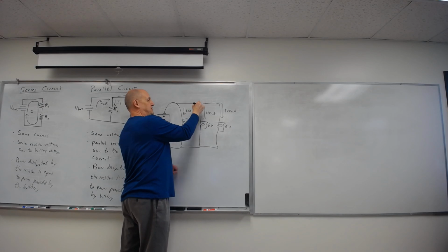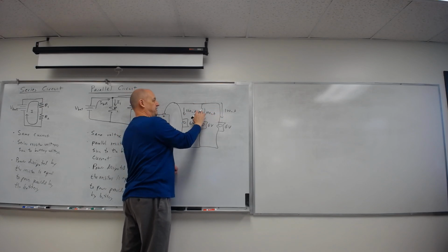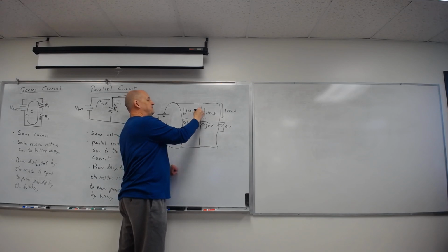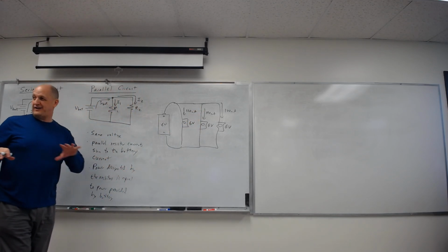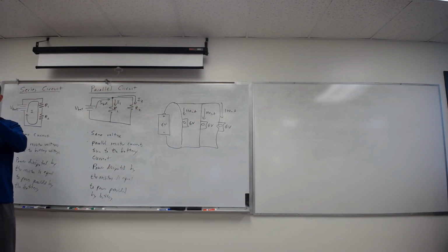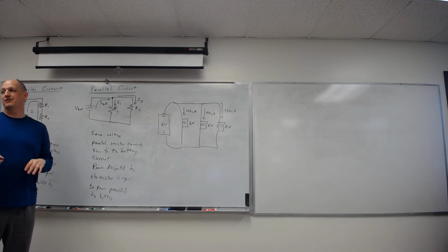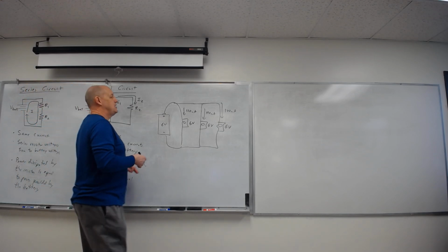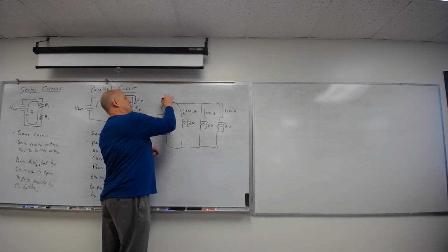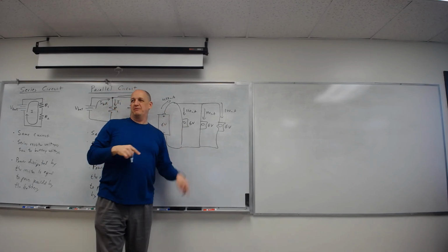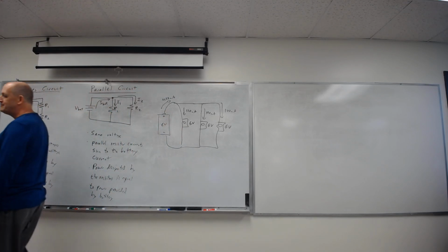I have to make sure I let this one flow on through to there and disconnect. So it's just this one. I showed a fair number of you that. If I didn't show it to you, you had to kind of make sure only the one's disconnected. So only one's out. Everything else is working. Then you put your ammeter on and turn that one on. And you would have had about 420 milliamps out of here, which is why this pulled down, because these things can't provide that kind of current very well.